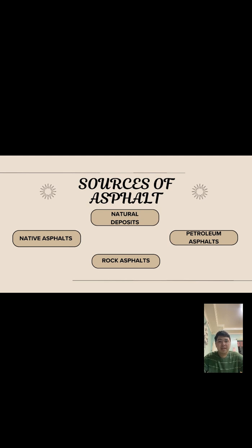Historically, native asphalt softened with petroleum fluxes was widely used as binder in highway construction. However, its properties can vary significantly depending on the deposit, particularly on the content of insoluble materials. For instance, the Trinidad deposit contains approximately 40% insoluble organic and inorganic materials, whereas Bermuda asphalt contains only about 6%.